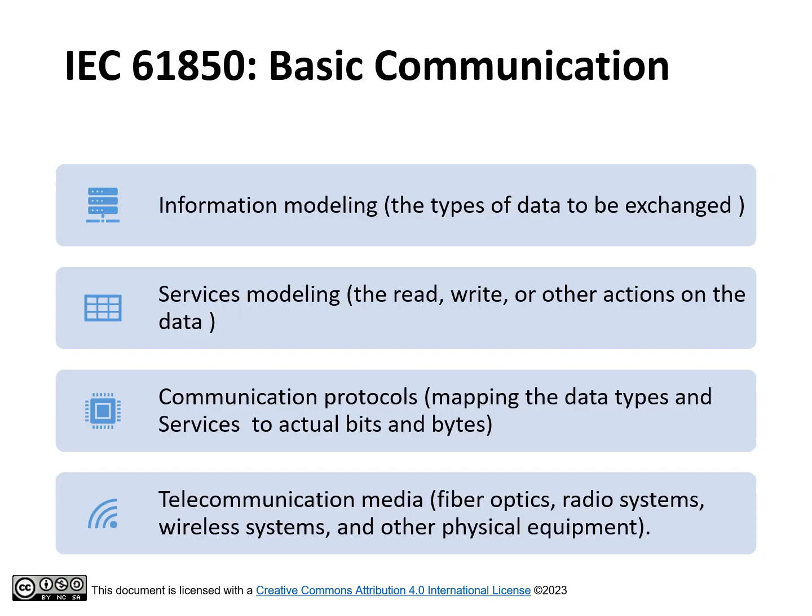The IEC 61850 communications can be delimited into four parts. Number 1, information modeling, i.e. the types of data to be exchanged. Number 2, services modeling, i.e. the read, write, or other actions on the data.